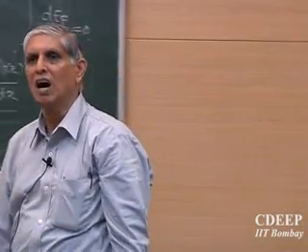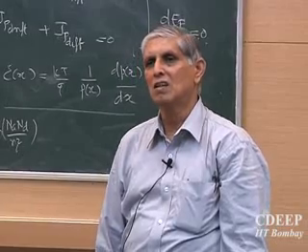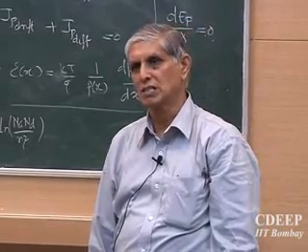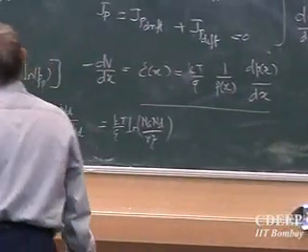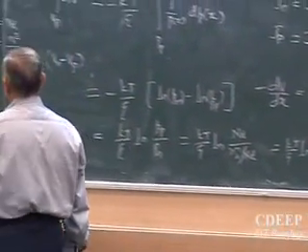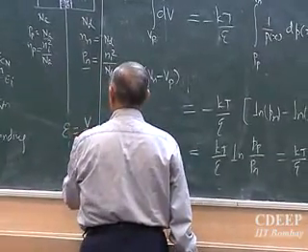So can you tell me when V0 will be larger? When either Na or Nd or both are larger. The larger the Na and Nd, the larger will be the built-in field. Is that correct? Now think of something interesting. Electric field is given by V by distance.